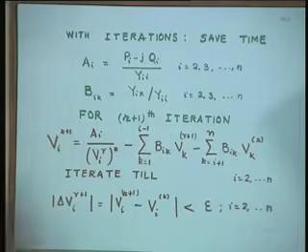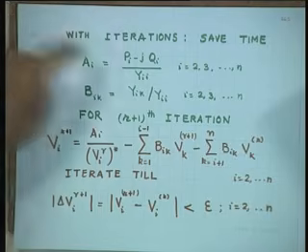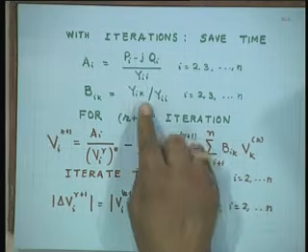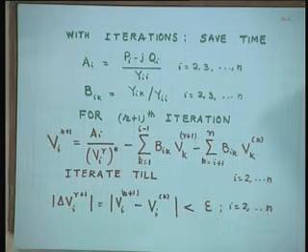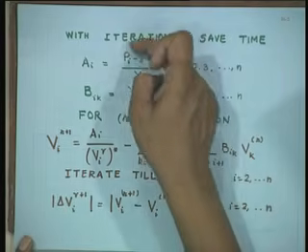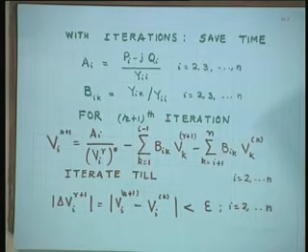Right. These are the two quantities which are part of that equation. Pi minus jQi are known to us for all PQ buses. In fact, they are specified by us. They are not going to change. Divide by Yii, this Yii is not going to change. I have already told you in 2 minutes how Y bus remains constant unless there is a change in topology. So why should this particular factor be a part of the loop?